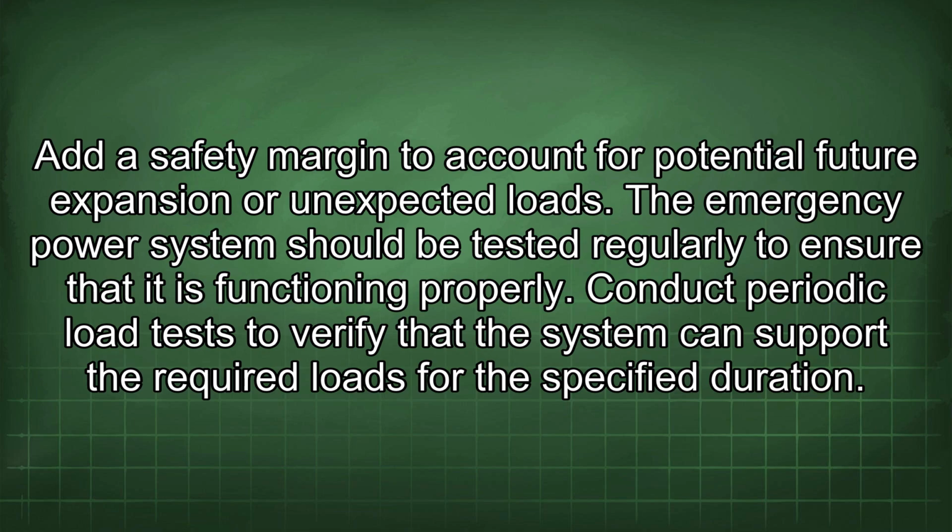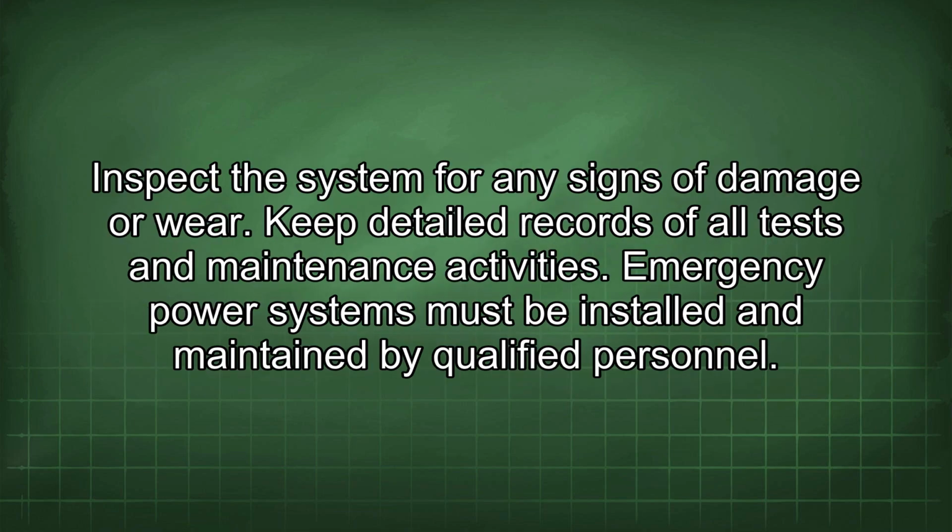The emergency power system should be tested regularly to ensure that it is functioning properly. Conduct periodic load tests to verify that the system can support the required loads for the specified duration. Inspect the system for any signs of damage or wear. Keep detailed records of all tests and maintenance activities.